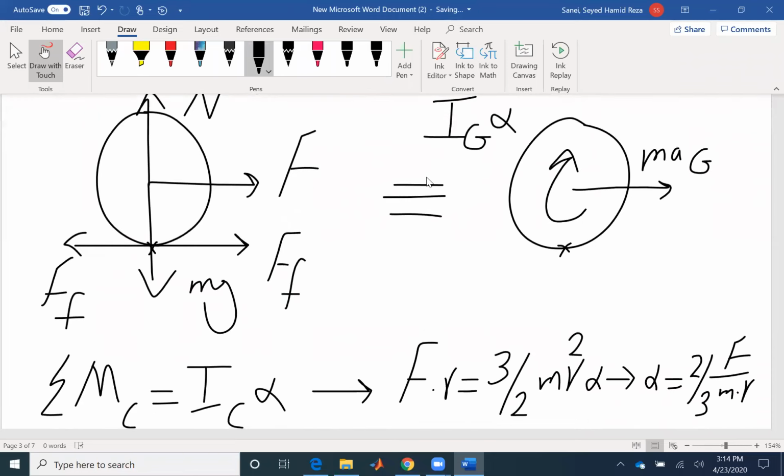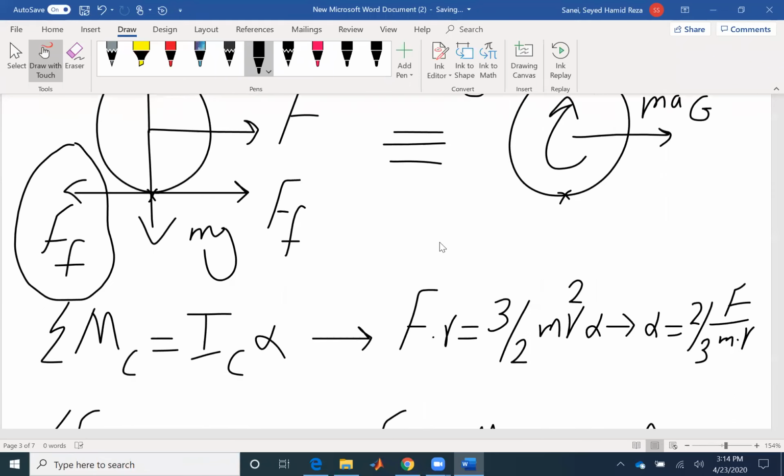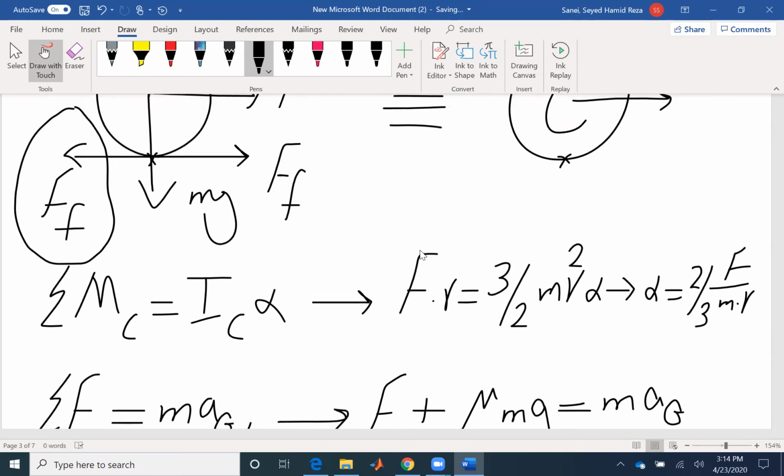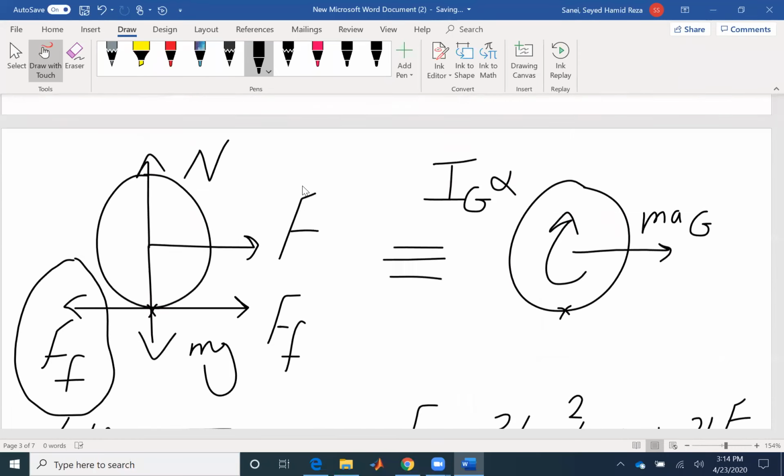So here, in case of rolling, the friction force is acting to the left based on the two equations that I developed. When force F is pulling the disk, there is a tendency for point C to be moved to the right, therefore the friction force is resisting that to cause the rotation and rolling of the disk.